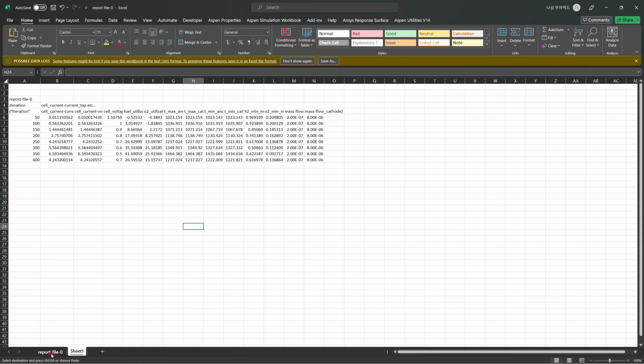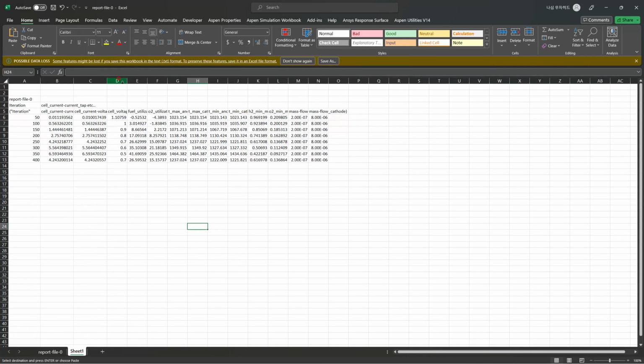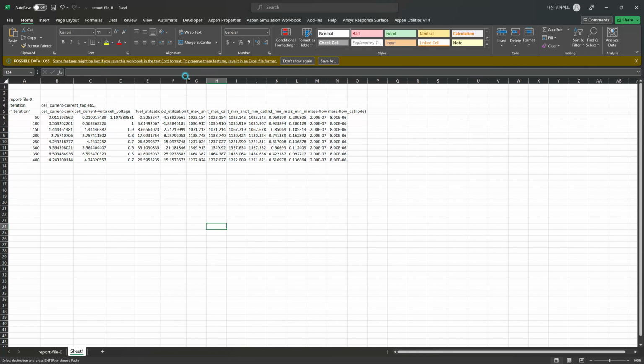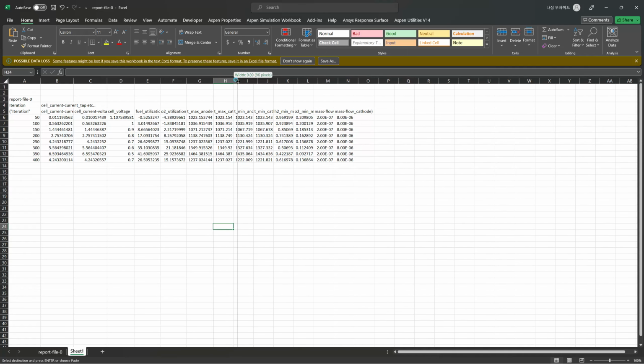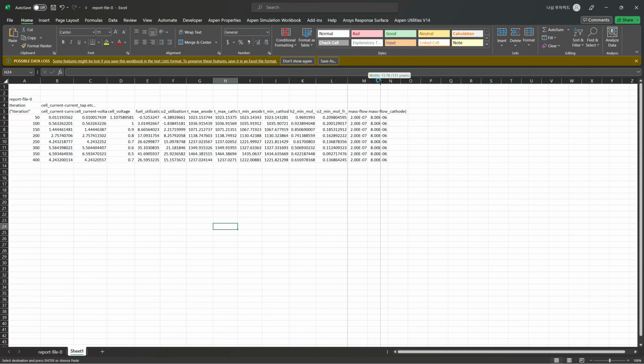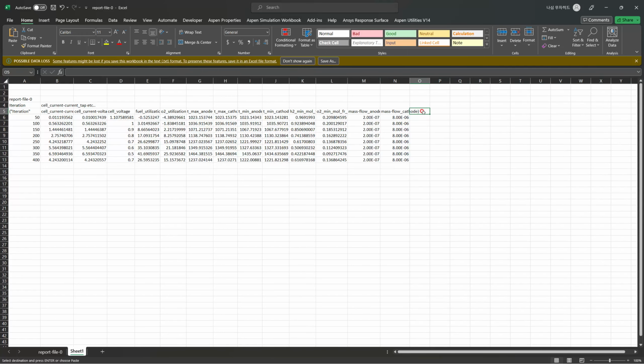A better way was to copy this sheet entirely and then delete the unrequired rows. And now here we can actually plot the IV characteristic, but for the IV characteristic it is important that we have the current density, not the actual value of current, although it will be the same. So we need to have an area. So if the active area is A active in centimeter square, we can actually compute this using Fluent.